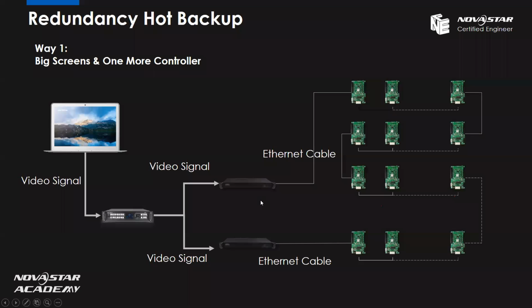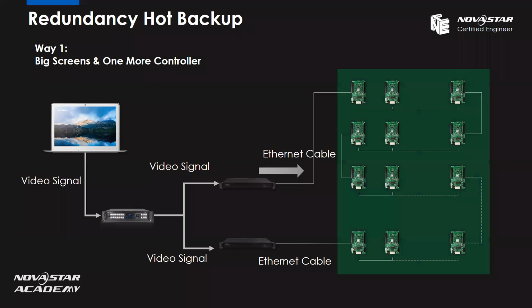So normally, if the project is working properly, the video signal should come in from the top one, which is a primary channel, and all the screen can get the video signal and shows correctly. But especially for the live show, if there is one cable broken in the screen, of course, the rest part of the screen can't get any signal from the primary channel.